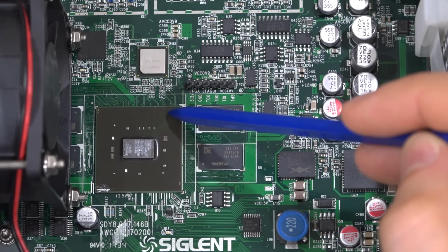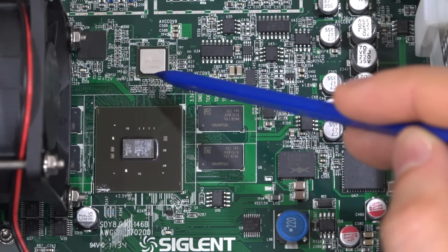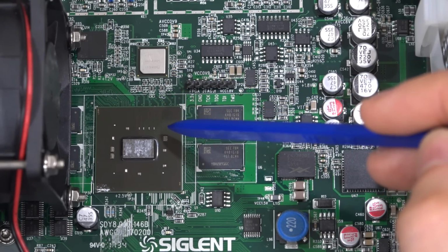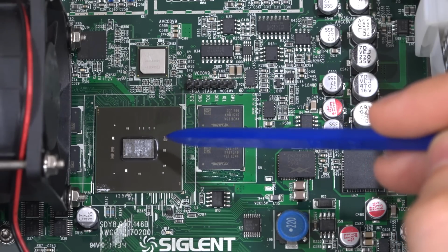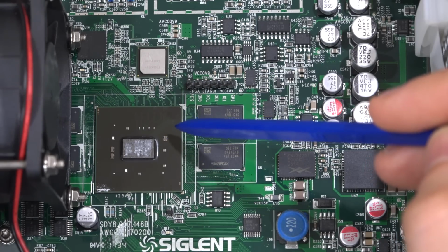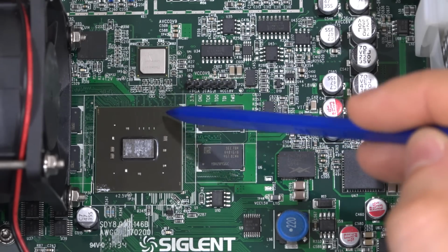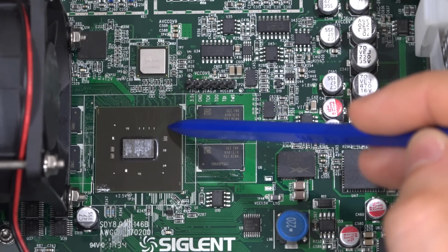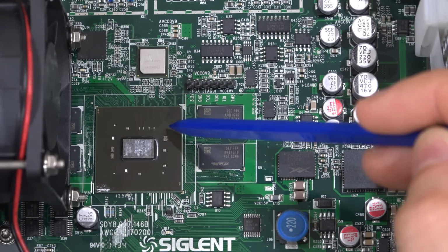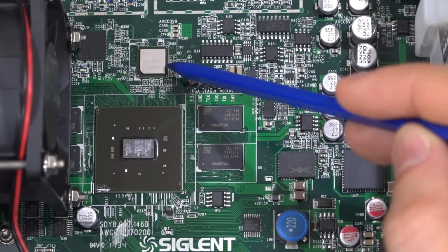Now the JESD204B interface of this DAC has 8 lanes all the way up to 12.5 gigabits per second. So that's the only way you can get enough data to these DACs, and at that mode you can only operate it at 1.5 gigasample per second, I believe. So this interface puts a lot of strain on the FPGA. And depending on how much FPGA bandwidth you have, how much memory you have, and how fast these interfaces can run will determine the maximum bandwidth you can occupy from the DAC at any given moment.